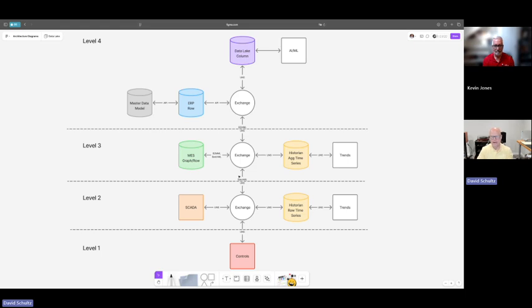So what I'm getting at is UNS: it's telemetry, it's time series, it's contextualized, it's not just your process historian data. But yes, the structure of that information is going to follow the unified namespace concept, where your topic structure follows the ISA 95 hierarchy or equipment hierarchy model. It could be MQTT. You can use AMQP. You can use DNP3, although I only run into that in power and very much power controls. But the point is that it's a common technology. It's not a bespoke point-to-point integration. Yep. Okay, good.